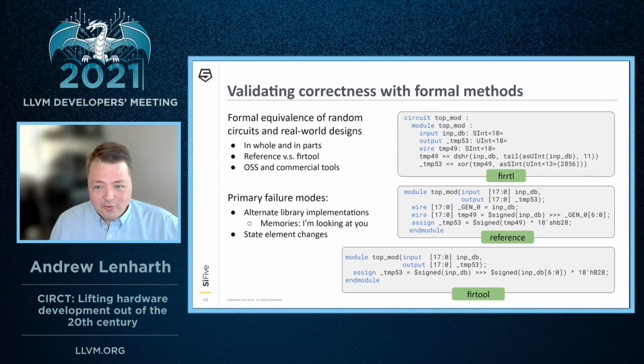Now, as helpful as formal methods have been, there are some places where they break down. The most annoying is places in the spec where different implementations are permitted. Since these formal tools are operating at a very low level of abstraction, at the Verilog level, when you have different behaviors, things stop matching.